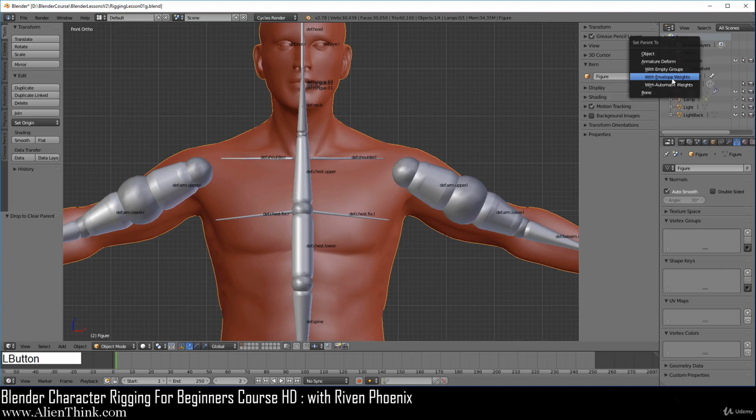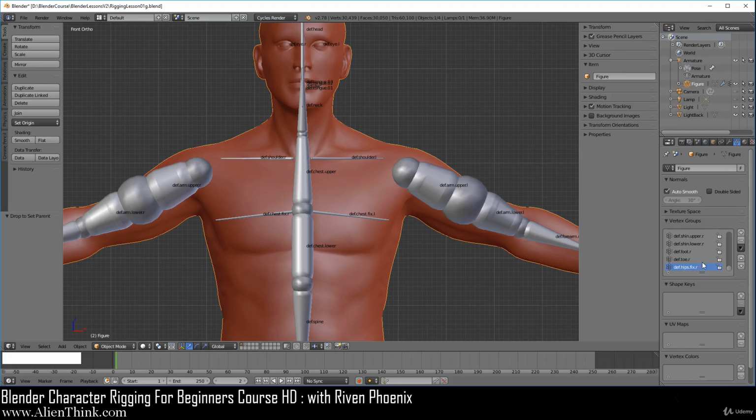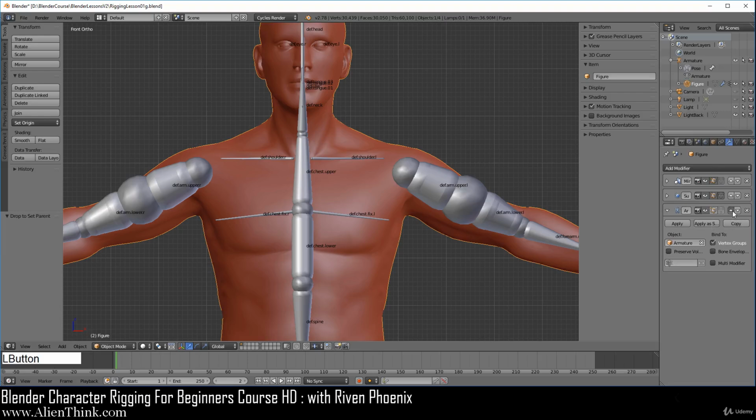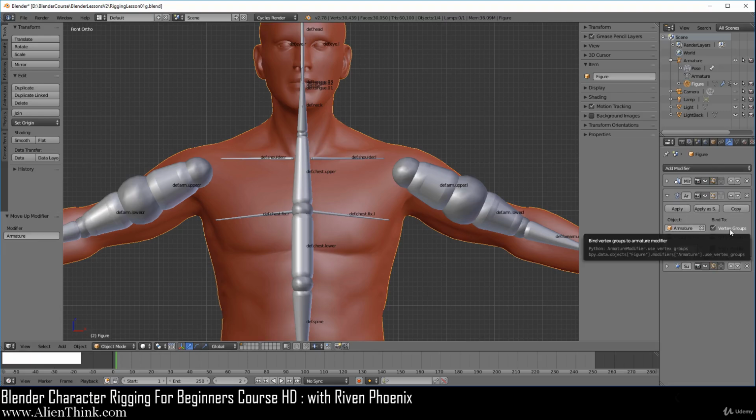Let's go ahead and click this. So you'll see it's just going to do the same thing, but this time it did not shoot rays out of the bones. It simply used that white space to capture these vertices. That's all that was going on over here. Okay, so now when you click on the modifiers tab and move this up, here we're going to use vertex groups.